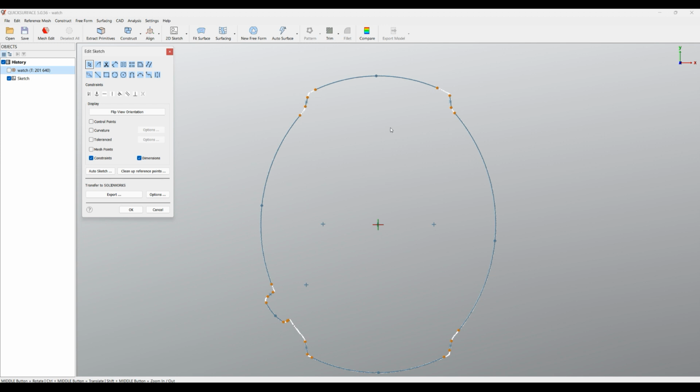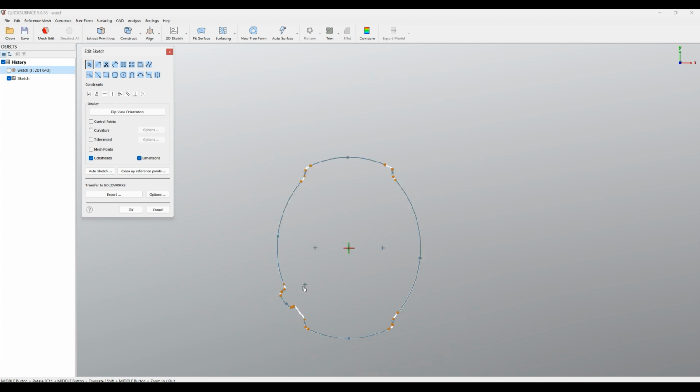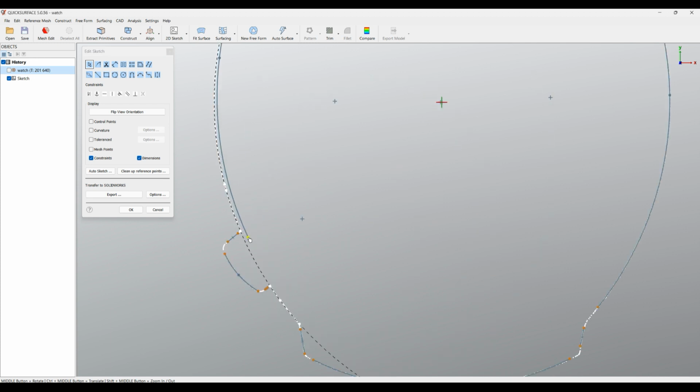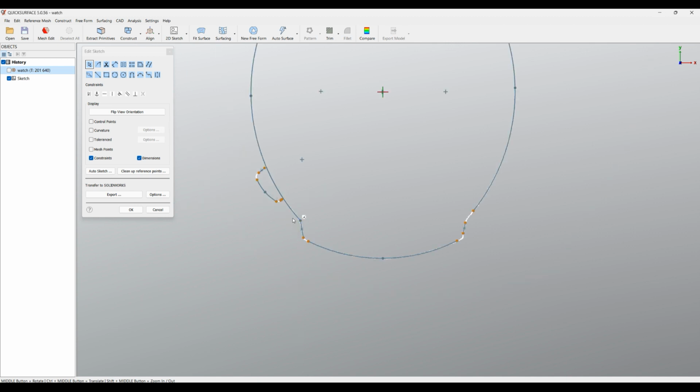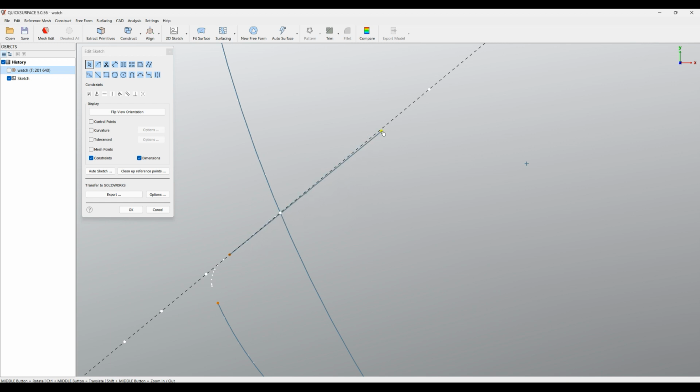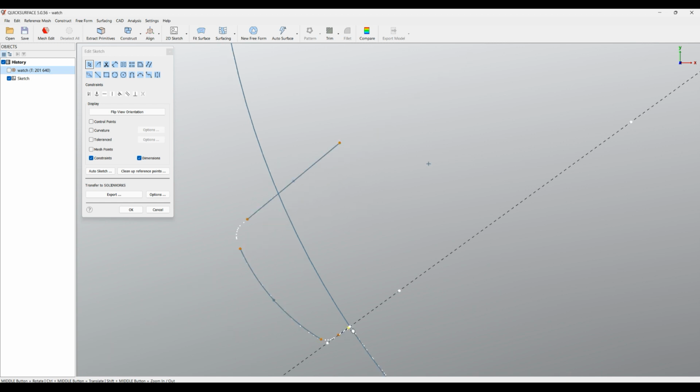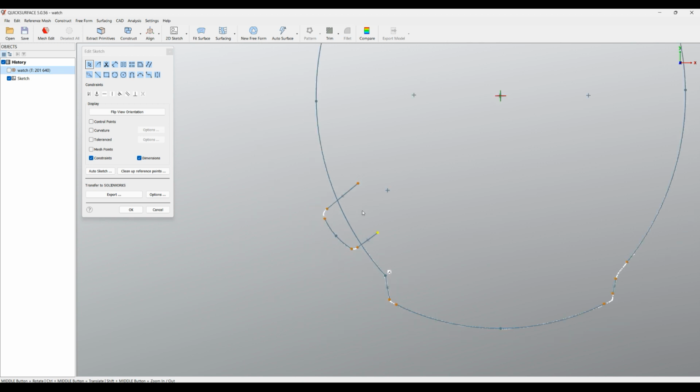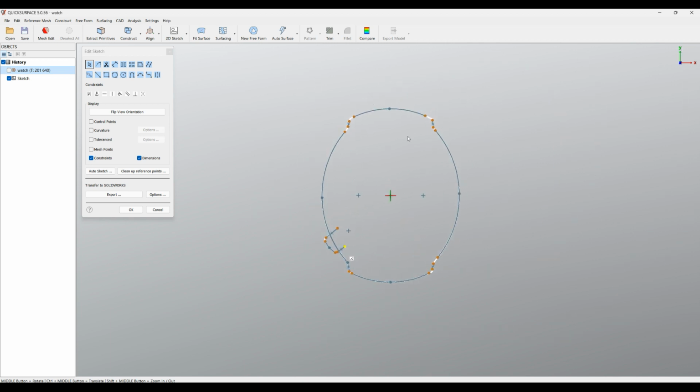As I have created my rough outline, I'll go back, and what I need now to do is just to connect all of these shapes. You can see they are in orange, which means they are not connected. In this case, as I showed you, you can just move, and what you see are these white dots. This means that where they intersect, and I can just simply go and snap here. Then I can just move this line and it will connect to this arc. In this case I probably need to extend this a little bit in. You'll see that later I will just trim this very quickly, and now I need a faster way to be able to join all these shapes together.